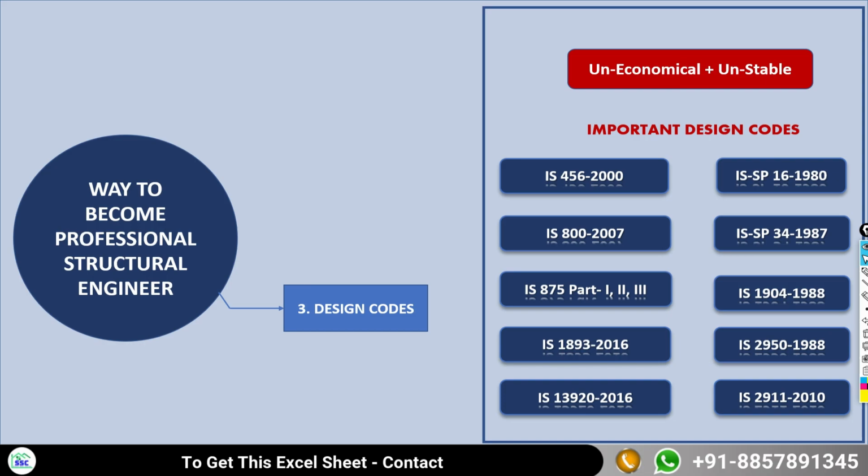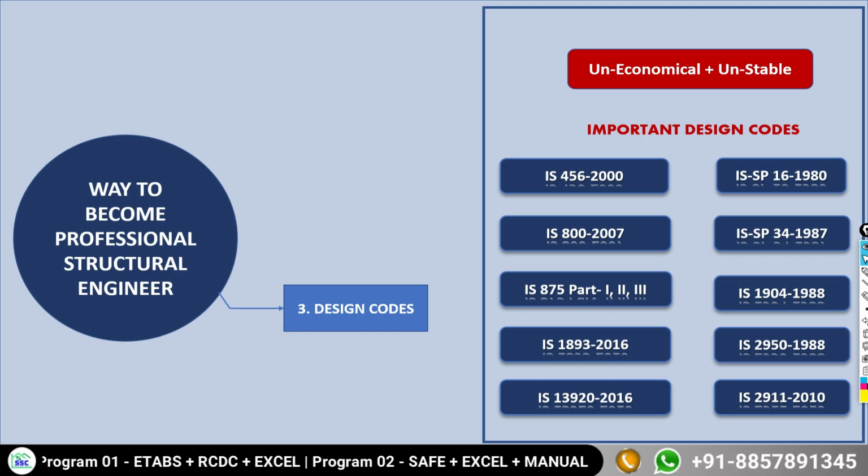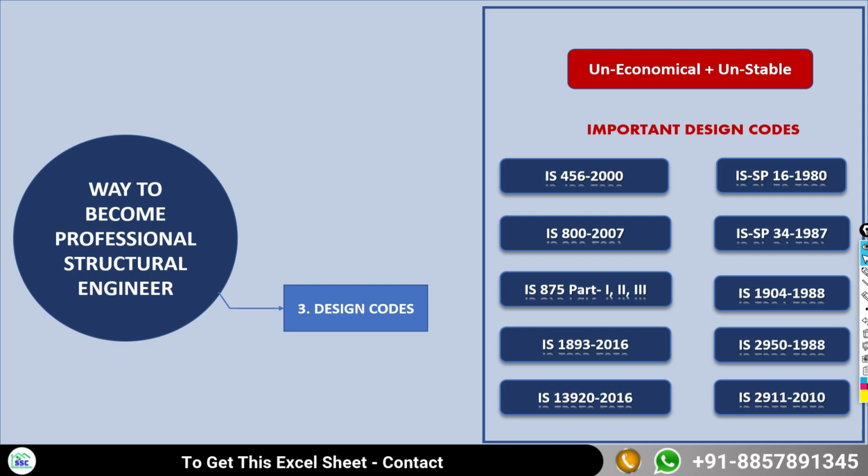Then if you are going to assign the load over your structure, there are different types of structure based on their utility. Some structures may be commercial, industrial, residential. If you want to assign the load for different categories of structure based on utility, how much load you have to assign will be given by IS 875 Part 2.